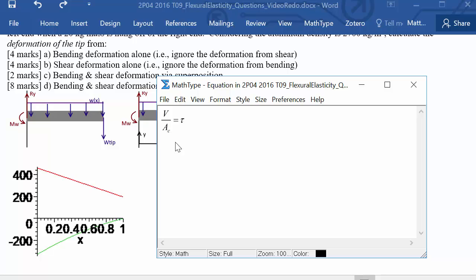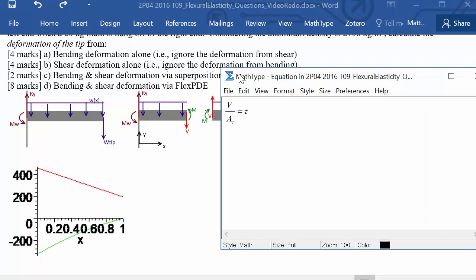And specifically the shear force that we've assigned in this picture, if we're looking at this V inside here, what is this? This is on the X face in the Y direction, kind of, right? Because V, as it's assigned going down here, is really the shear force on the X face in the negative Y direction. So that would really be negative tau XY, yeah?